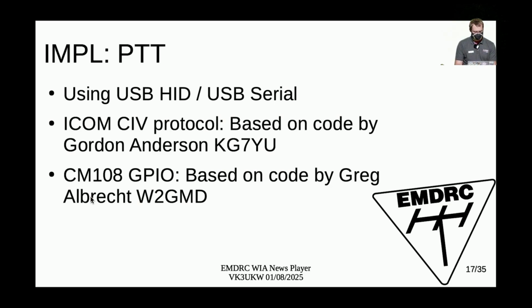And then the next little thing that we need is a PTT control, and that's the thing that I homebrewed. What I implemented in the software here is both the ICOM CIV protocol, so the regular ICOM serial control protocol, and also the CM108 GPIO. The ICOM CIV protocol you can use with any modern ICOM rig that you just connect via USB, or of course the older ones via serial.